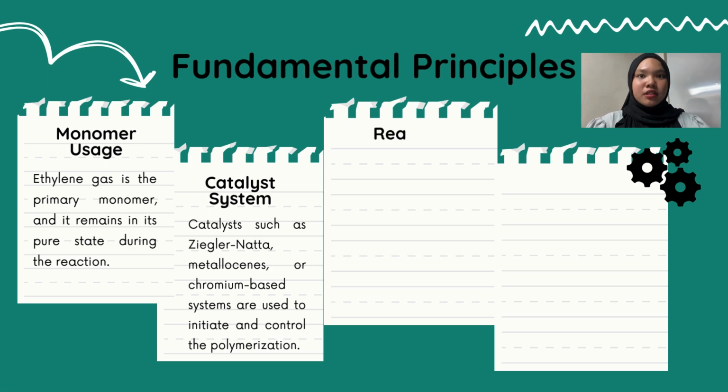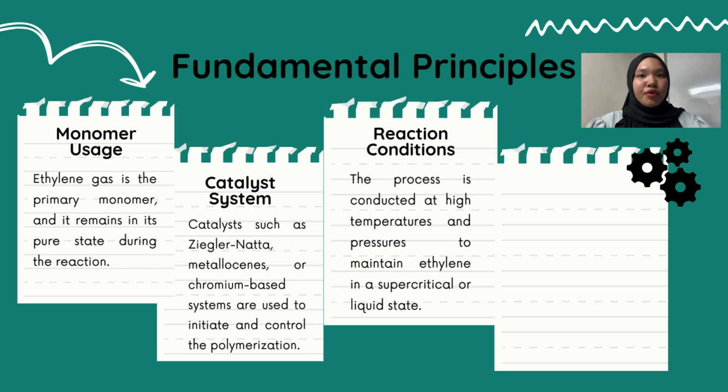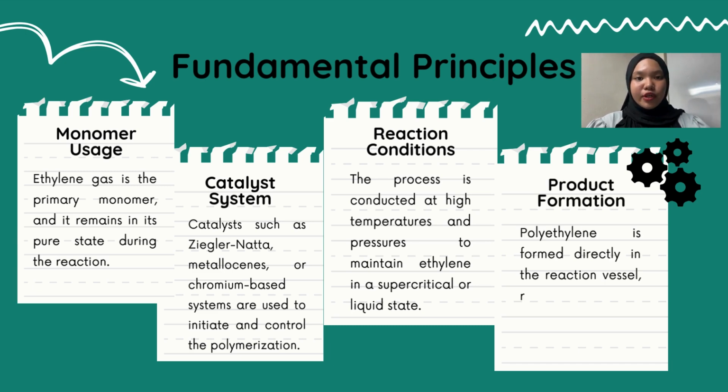The third one, reaction conditions. The process is conducted at high temperatures and pressures to maintain ethylene in a supercritical or liquid state. The last one, product formation. Polyethylene is formed directly in the reaction vessel, requiring minimal purification.